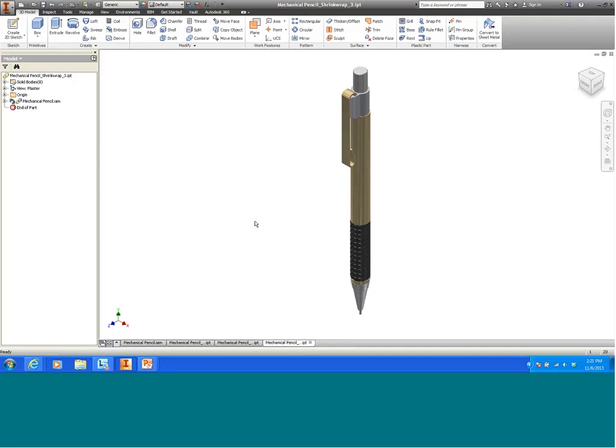So just to summarize quickly, in terms of simplifying using the shrink wrap tool, there's unfortunately no way that you can pick and choose components that you want to include or exclude. The only way to do it is with those visibility and size percentage settings.